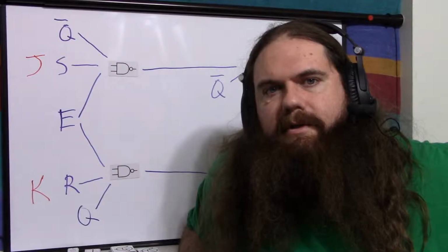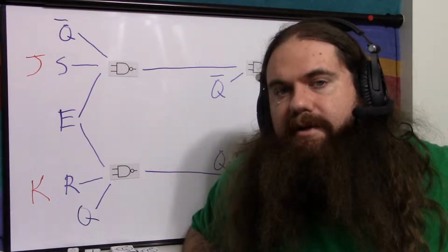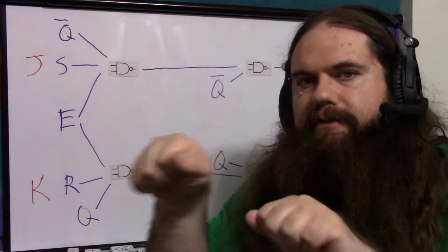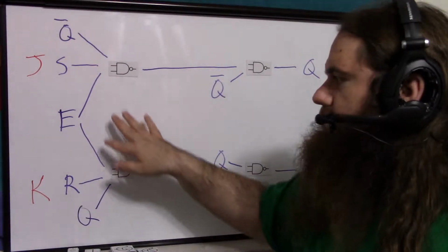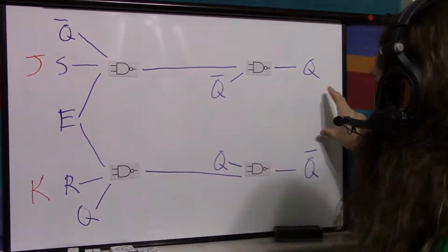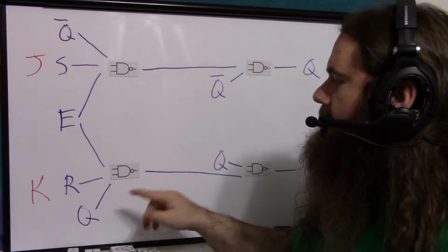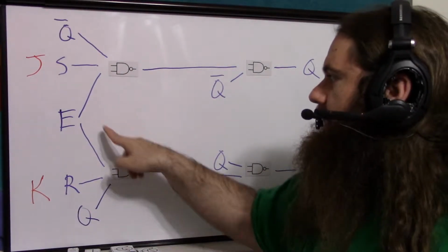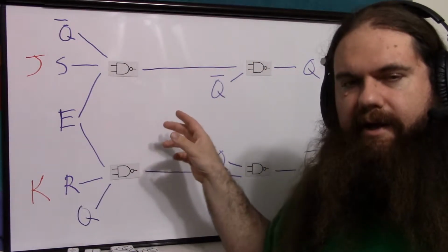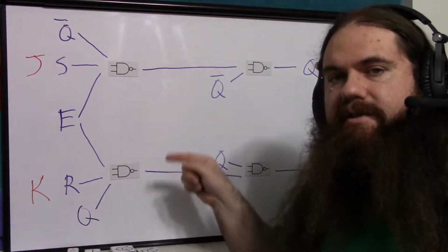There's something called a JK master-slave flip-flop. Basically, we just add another layer to this, and it has this internal interlocking active on each half of the clock signal. It's really cool. But if we just perform the thought experiment, just to understand this, if we pretend that this is edge triggered and it's always fine, then we at least understand it. And all we had to do is add Q and not Q to this. And the enable, just like before, so this would be still the same 8 transistors, and then you can optimize by having 1 transistor for enable that's shared by the 2. So this is still 7 transistors.